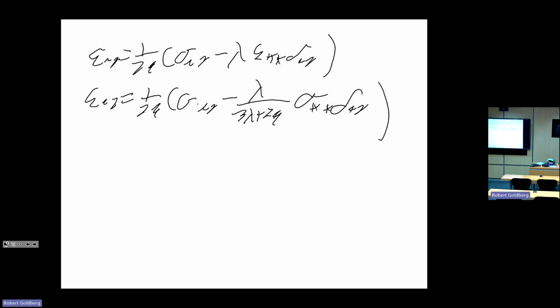This is our elastic constitutive equation with strains in terms of stresses, in terms of the Lamé constants. What we're going to do next time is take these Lamé constants and relate them to the engineering constants that you know and are familiar with.